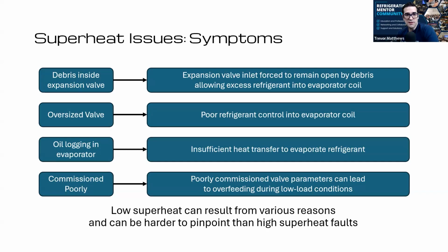And the very first point there, Chris, debris inside the expansion valve. I think that is one of the biggest ones. When I used to work for the manufacturer, doing a lot of electronic valve training, I would go to events and talk to all the competitors, and we had the same thing as a manufacturer. Most of the issues were debris inside the valves. So this is something that you really want to take a look at, because all the big valve manufacturers are doing a good job. They've got quality control. They're spending millions of dollars to make sure a good product comes out. Do issues happen along the way? Totally do. But there should be absolute zero dirt or debris inside a refrigeration system.